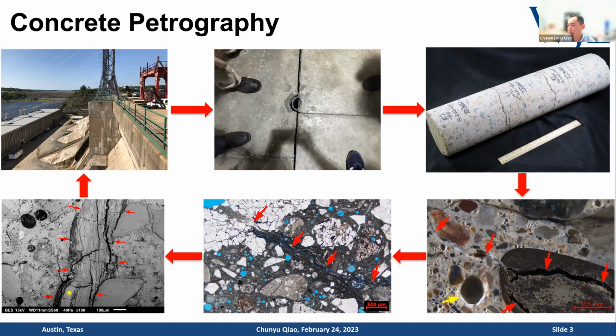So as I said, identifying ASR is not difficult by petrography. The question for us, and the most interest for the client, is more about what is the stage of this reaction and how much more damage this ASR reaction can impose onto the structure. So to answer that question, a lot of times we will obtain sample cores from the